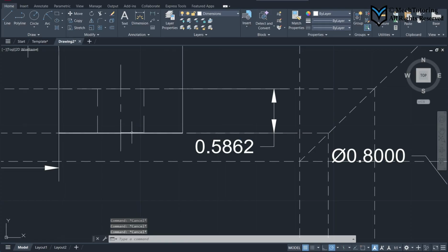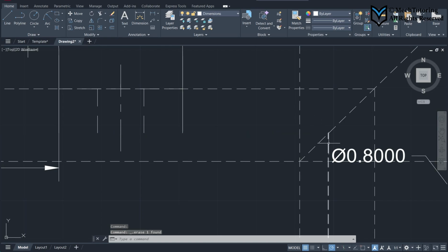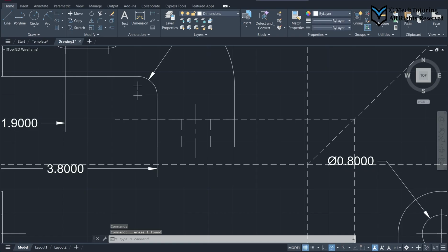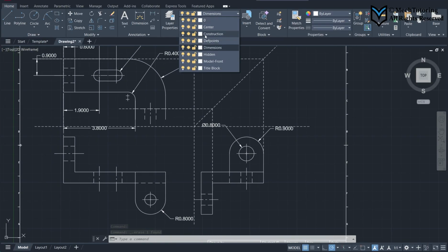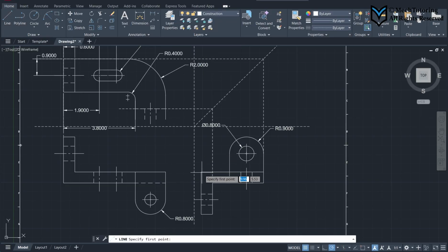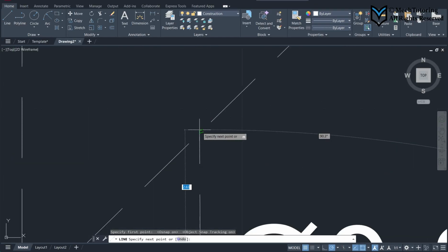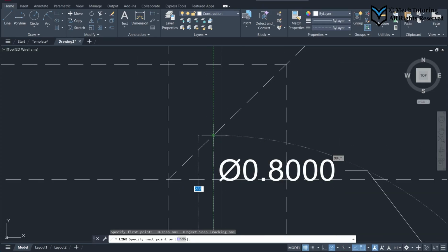Let's delete that dimension, remove that line, and keep every other line over there, and delete this line and this line, because the end of that we didn't select properly using construction lines. So I'm gonna create a new construction line and make sure the snaps are on. Then zoom in and make sure you end on that line properly. Okay, you end on that line.